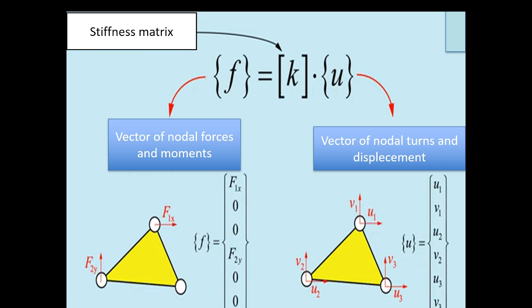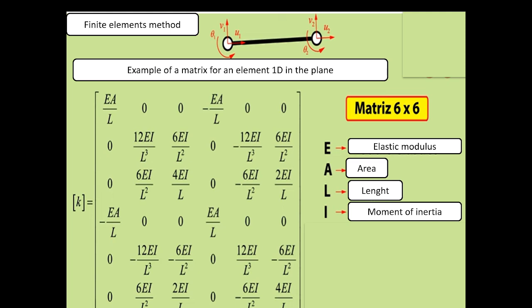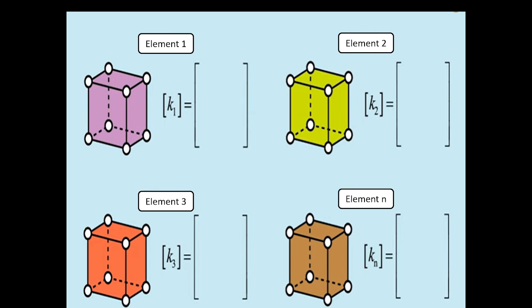This is where the next important concept comes into play, the stiffness matrix, which defines the relationship of the displacement and rotation at the nodes with the applied force. The coefficient matrix is obtained from the equilibrium equation governing the element's behavior. It's complex. Just remember that the method transforms a differential equation into a linear matrix. These stiffness matrices are always square matrices, and their size is defined by the degrees of freedom of the element. However, elements are not isolated. They work together in the mesh.